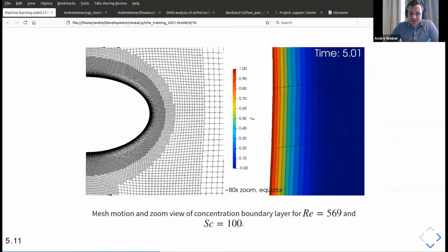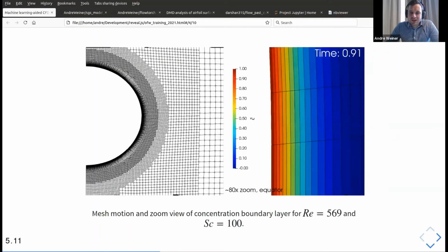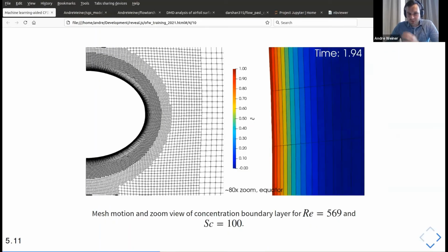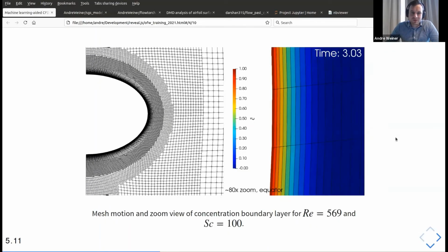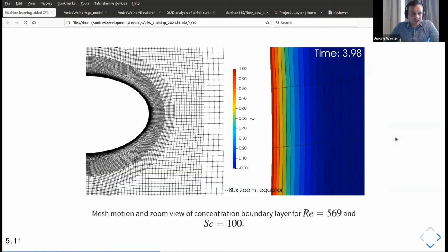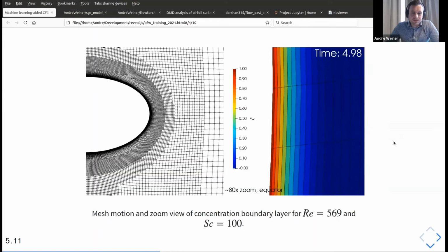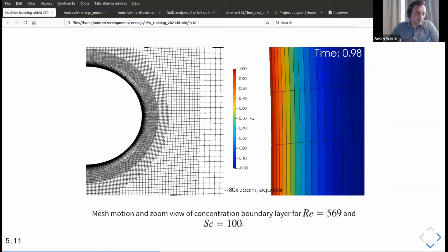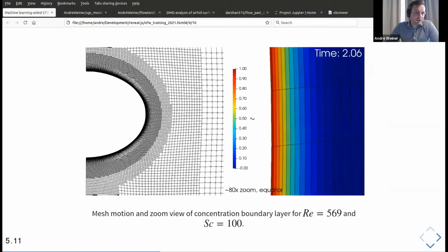And you see how the boundary layer is changing over time as the bubble accelerates, because our inlet velocity is time dependent, right? And how we always have some cells in the boundary layer, so as to resolve the boundary layer properly.